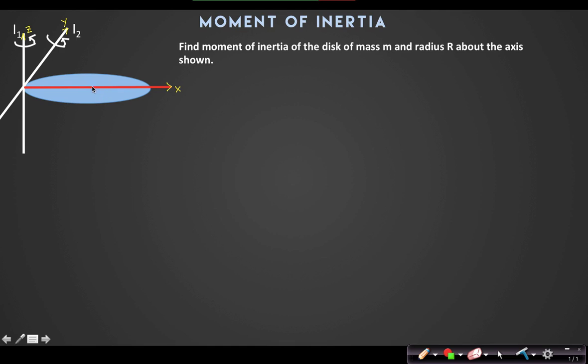Good. How can we do it? Suppose it is the center and center of mass both. Can I find the moment of inertia about these two axes first? Suppose this is I_y'z' and this is the y-axis, this is the z-axis. Look, about all the axes I have drawn, about which axis of rotation do I know the moment of inertia?